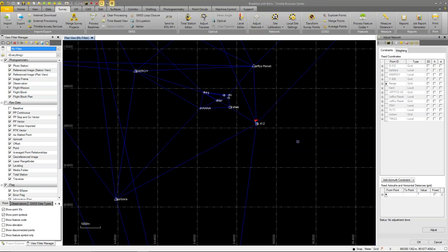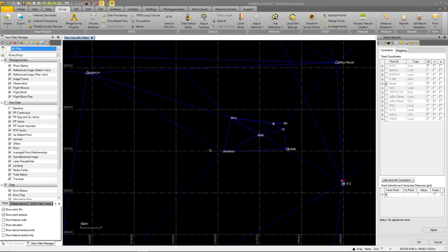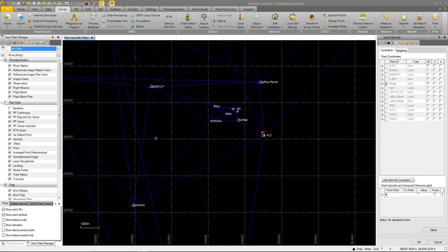I mean, in the end you have to report the coordinates for this thing depending upon what you're going to use them for. If it's a project where you're going to do some kind of construction work in this area, and you're doing a boundary survey of points in your project area that you want to use for a later construction project, you're probably going to tie it to some kind of control that's a little bit more local, maybe not a national network, but a city or a county, or some published set of coordinates from a local agency rather than the federal agency. But the choice is entirely up to the surveyor what he wants to use for his final control values.